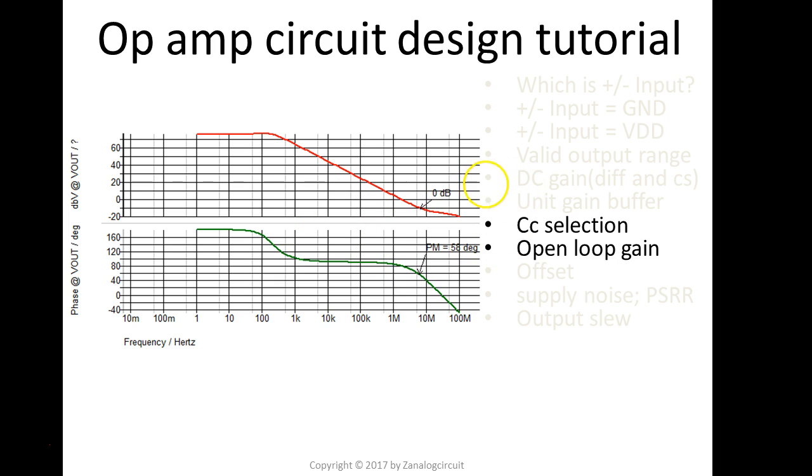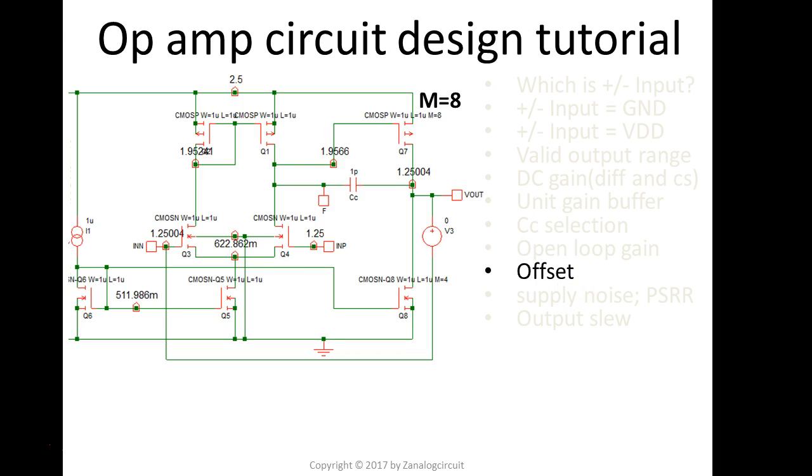Opamp compensation. By the way, in most cases the unit gain buffer is the worst case for loop response, because what it does is feed all the output back to the negative input, which is the worst case in terms of the AC loop gain or phase margin. So at least according to the AC analysis, it looks like the compensation cap we picked is good enough.